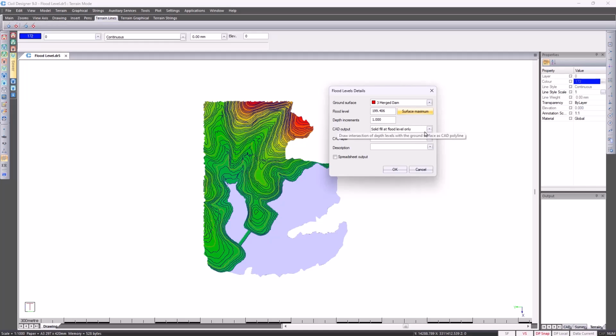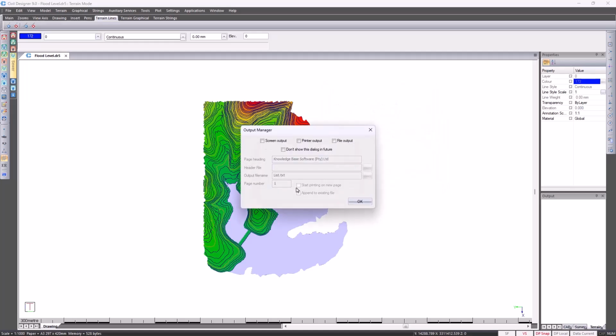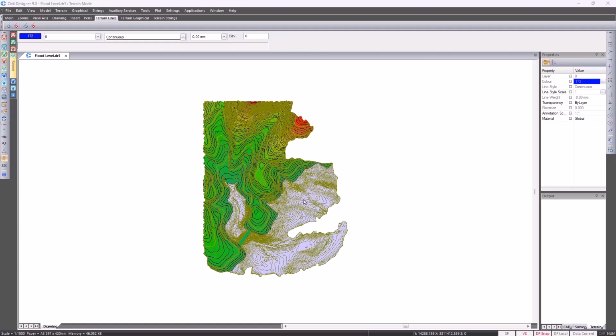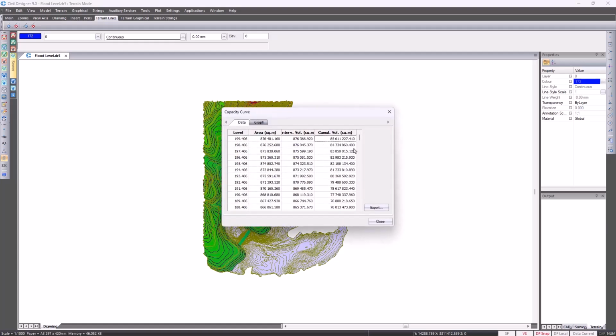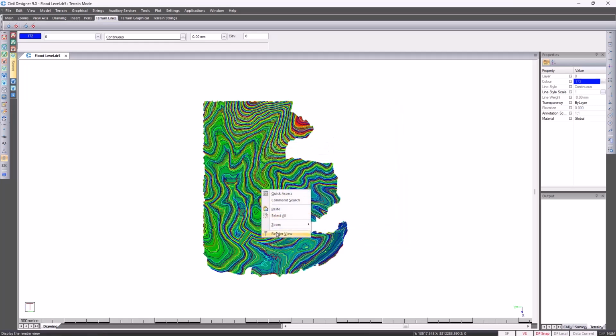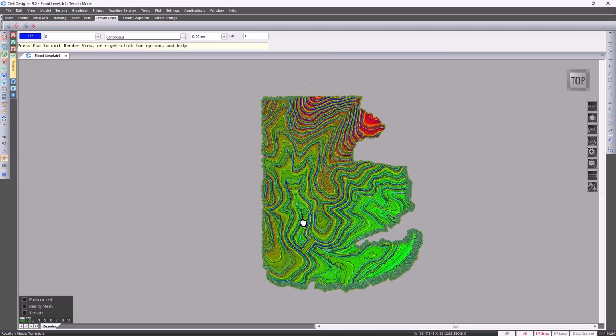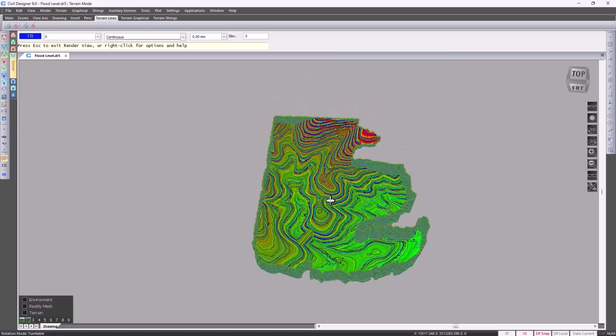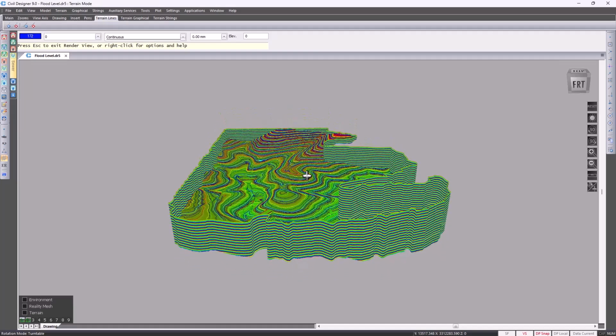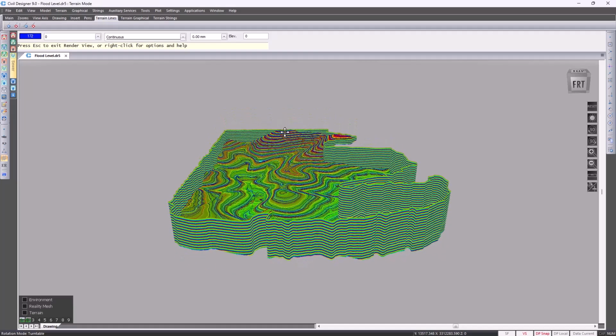Again, you could go and specify which CAD output you'd like to use and make things interesting. I'm then going to put in a polyline at every depth increment. Looking at the new cumulative volume. If you go and render that now, perhaps easier to understand what the function does when I show it to you in the 3D rendering. Taking the highest point, projecting that along the perimeter of your site, and then calculating the volume.